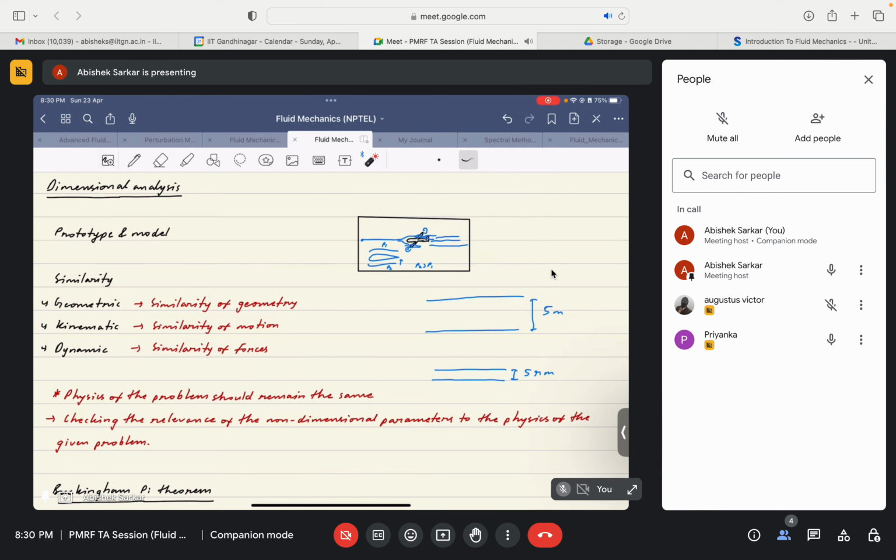Capillary action. Yes, absolutely correct. So capillary action becomes quite significant in the case of such small scale pipes, which you might have studied in the earlier lectures when we discussed capillary rise, how small diameter pipes, if inserted in a liquid, could cause a liquid head to rise above that small tube, right? Basically because of the capillary action, and that is occurring because of the surface tension effects, right? So those effects come into picture when we are dealing with micro scale.